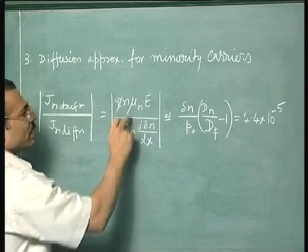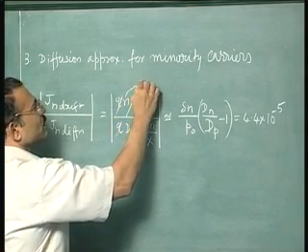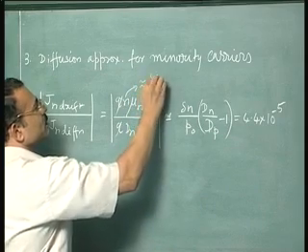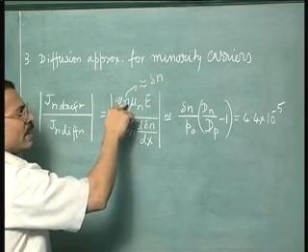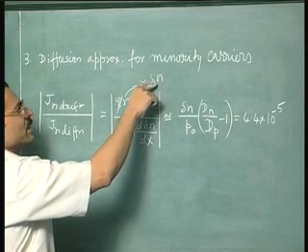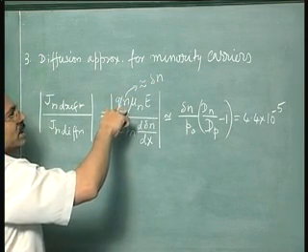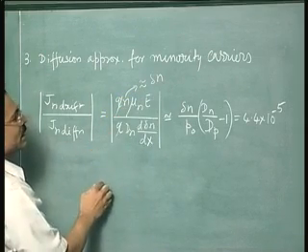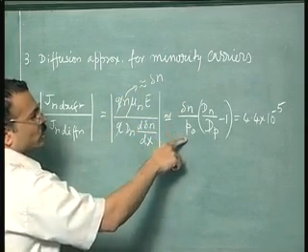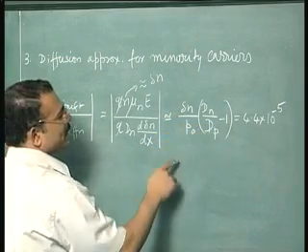Okay, where now here n we must recognize is approximately equal to delta n itself. This is because for minority carriers the excess carrier concentration will normally dominate over the equilibrium concentration. So we can simply replace n by delta n approximately over most of the device, and therefore your result will turn out to be of this form: delta n by p naught into dn by dp minus 1.